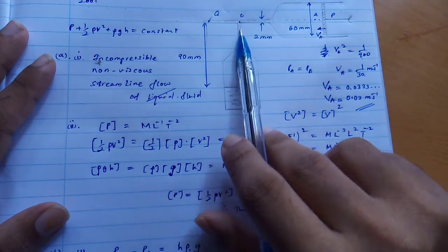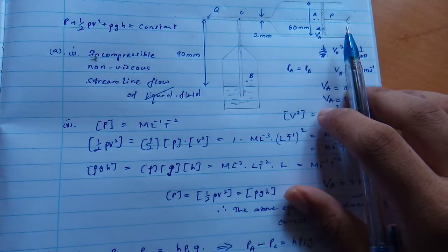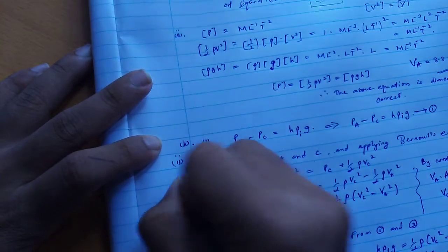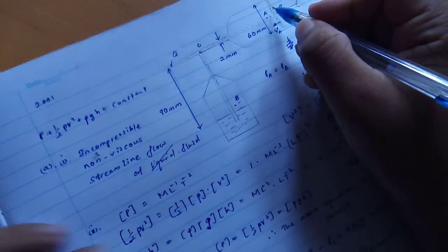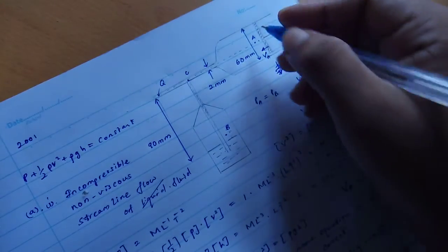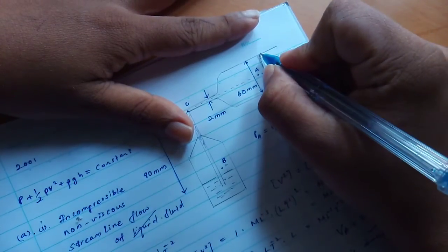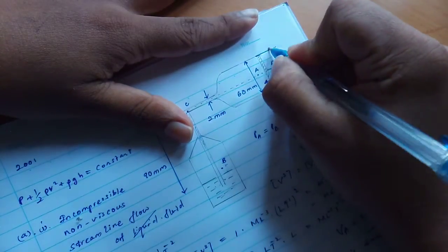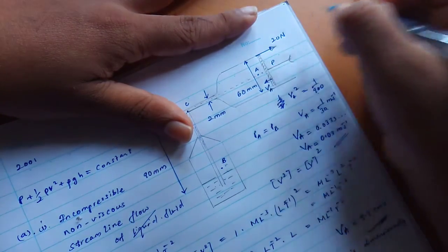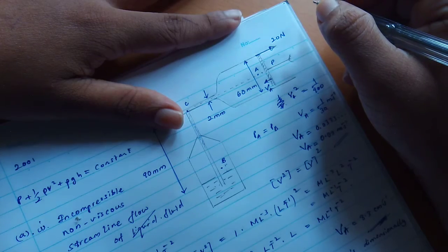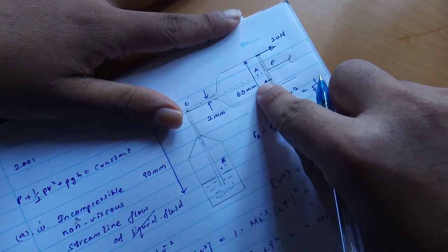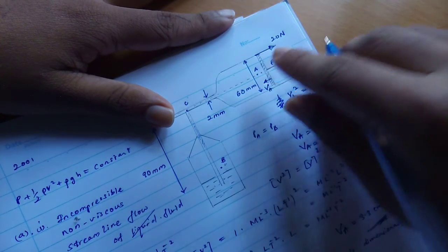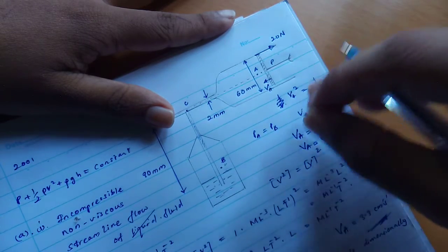Okay, and then we have one last question, which is under B part, Roman number 2. I'm writing here: if the net resistive force acting on the piston of the pump is 20 Newton. Resistive force means it's opposing the direction of motion, right? So here we have resistive force 20 Newton. Determine the force that has to be applied on the piston in order to maintain the speed calculated above.